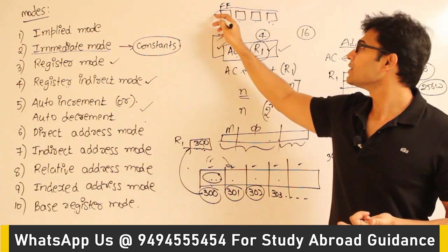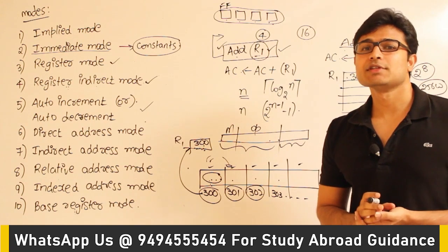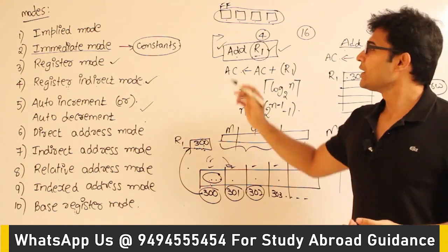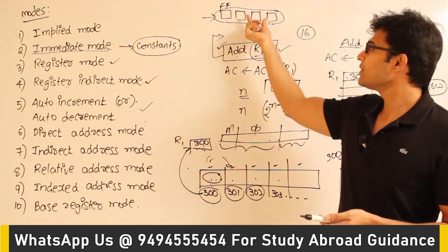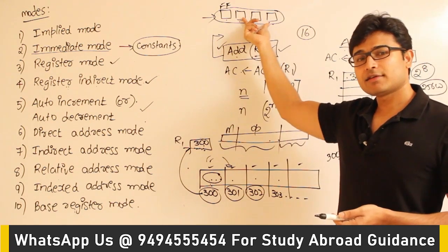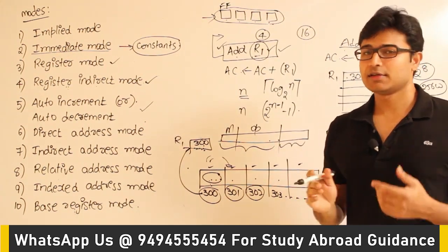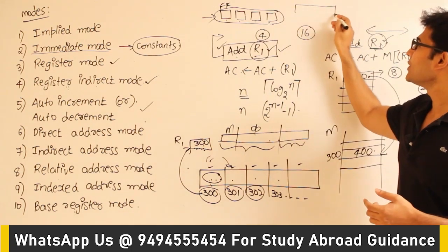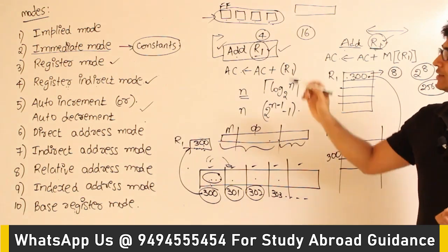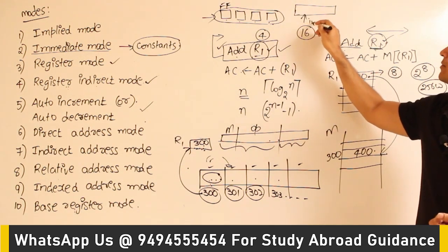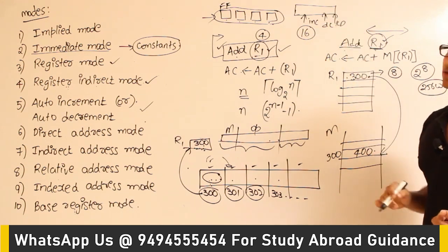Therefore, a register circuit also has connections using which it can be used even as a counter. If you give it a clock, we know that a counter will increase by 1. Therefore, incrementing and decrementing a register can be done easily. That is why, as I'll show you later, a register is not just going to have read and write. It is also going to have increment and decrement control signals. A register can have an increment signal, a decrement signal, as well as a load signal. Got it?